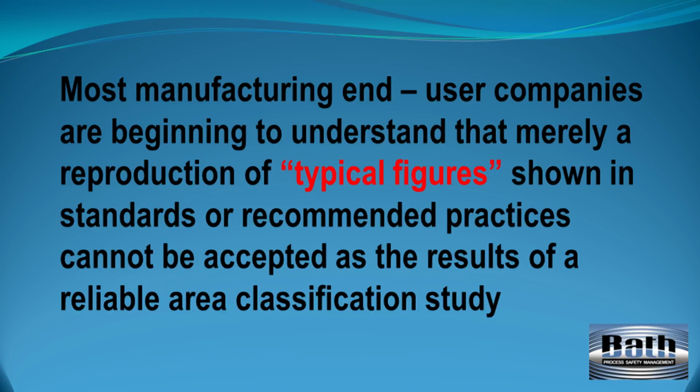Hazardous area classification is primarily concerned with the elimination of electrical equipment and its associated wiring as a potential source of ignition. Most manufacturing end-user companies are just beginning to understand that merely reproducing typical figures shown in standards or recommended practices cannot be accepted as the results of a reliable classification study.